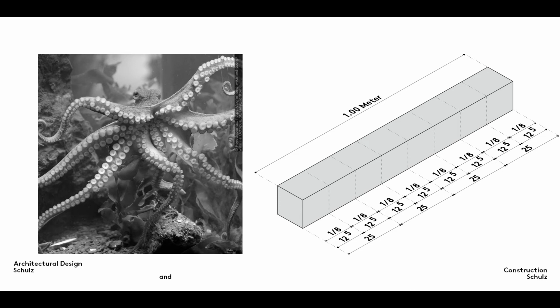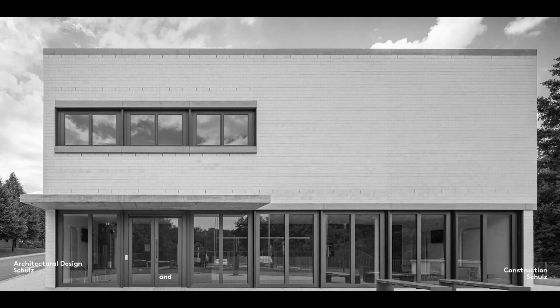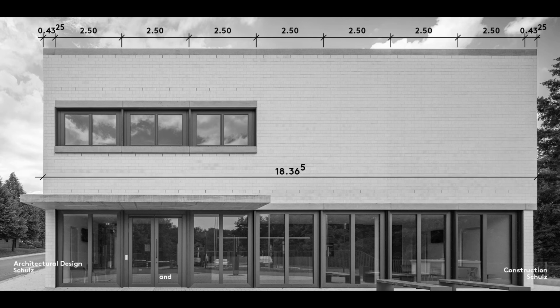As you know from our lectures last semester, the dimensions of industrially produced bricks and blocks are generally based on the octametric system, that is to say 1/8 of a meter. Taking into account a 1 cm wide butt joint and a 1.2 cm high bed joint, a typical normal format brick is 24 cm long, 11.5 cm wide and 7.1 cm high. When a facing skin is built using this type of brick, the exterior dimensions of the building also have to follow the octametric system to prevent the appearance of the brick bond from being spoiled by cut bricks.